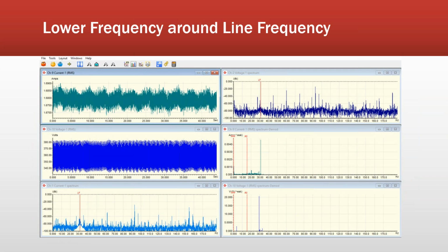What the data looks like, and what's really important, is the resolution, because a lot of the peaks come in with multiple speeds ranging from 14 to 20 RPM, all of the speeds of all of the components in the gearbox, all of the bearings involved, and then the generator, whether it's running at 20 hertz or 30 hertz or 1200 or 1800 RPM, or if it's overseas, maybe 1000 or 1500. Now, I say that because it's very important to understand the speed.